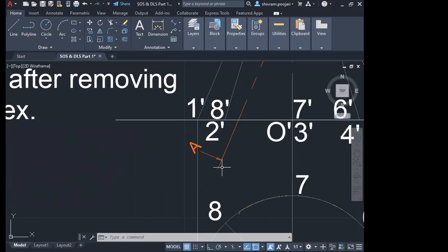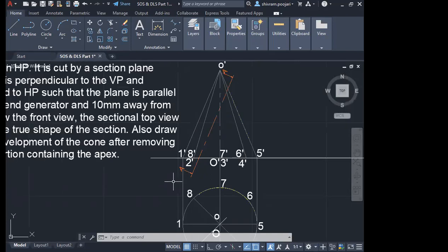What I told you at the start: the center line is long dash, short dash, long dash, short dash, long dash, short dash. But the long dash, short dash is also a section line, including the ends to be thicker. Okay, including ends to be thicker.